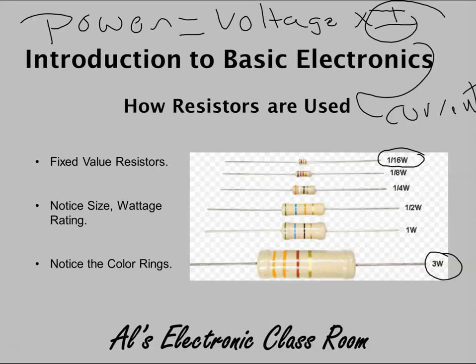and I say that the amount of power that's dissipated by the resistor, and I'm using specifically resistor here because that's what we're talking about, is a 1/2 watt, then the wattage rating of the resistor that I should place inside this circuit would be a 1 watt resistor, because what we want to do is overcompensate it.